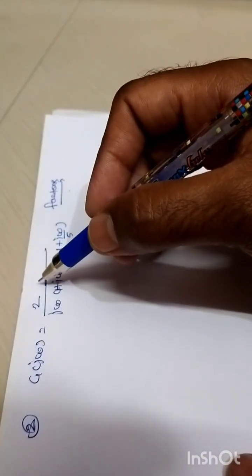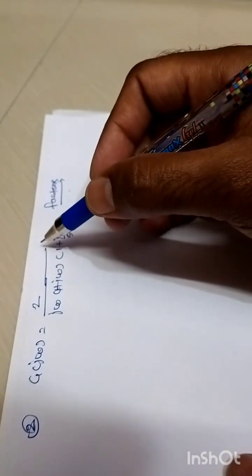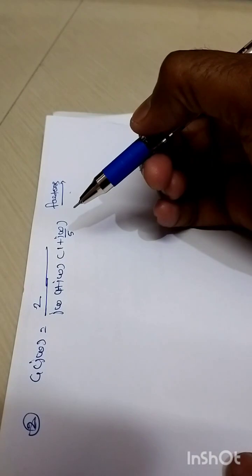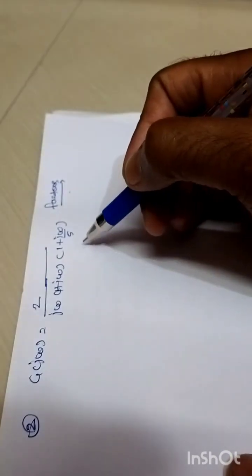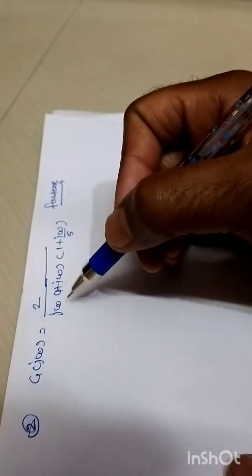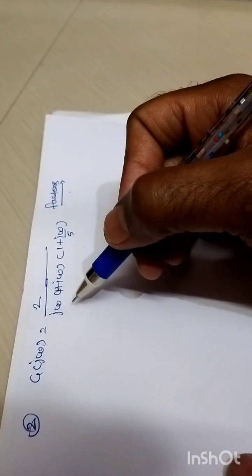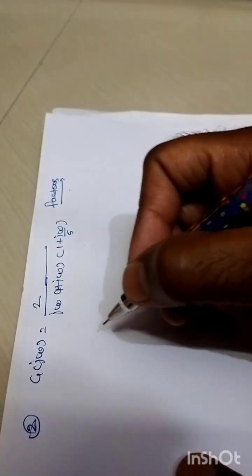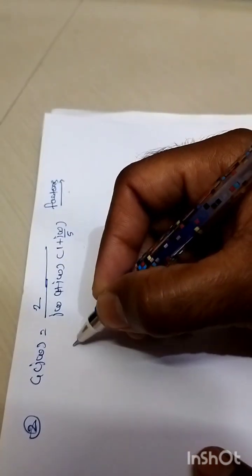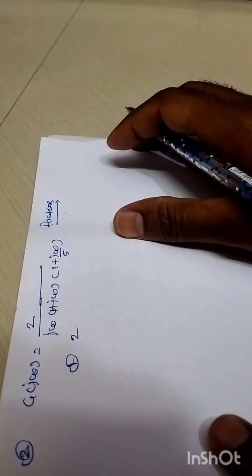Here we don't have any S domain term or j omega term located in this numerator polynomial, so we are not having any zeros. As far as the poles are concerned, there are 3 identical terms belonging to j omega in its denominator, which means there are 3 poles we are having with us, right? So one by one we will enlist all these factors. The first factor is nothing but this constant term 2, right?